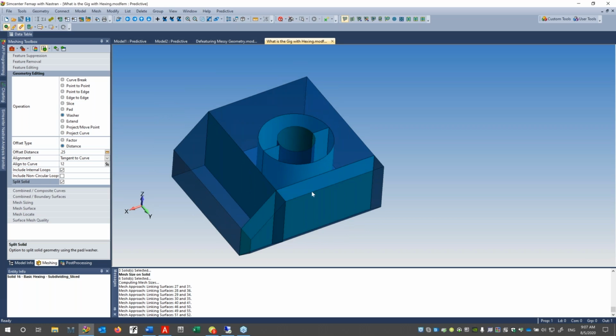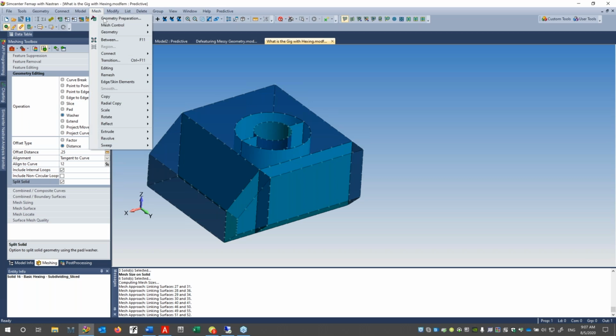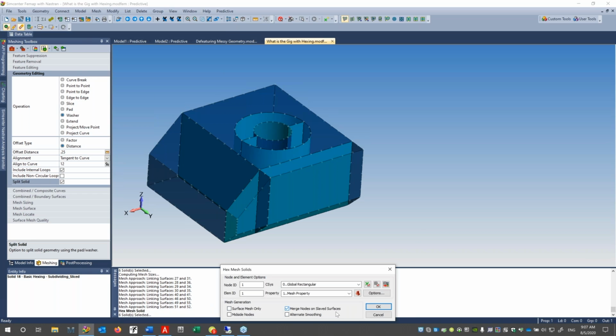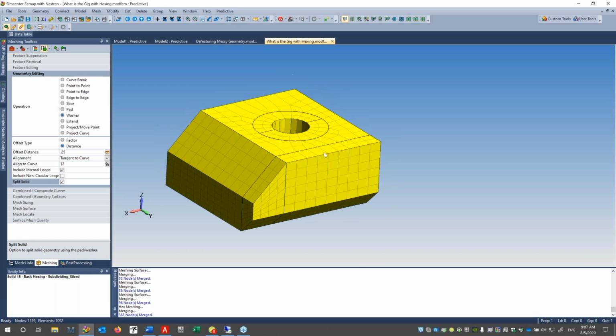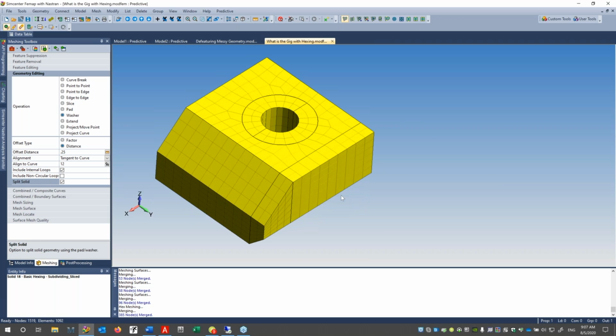sets up the priority. But once you get into the swing of things and think about a solid and pushing a mesh forward through the structure and how it behaves and the linking on it, how it thinks as a hex, it's really powerful. And you can figure out how to hex almost everything after a while. Once you understand the theory, you can see how it pushed it through with the hole, and everything is groovy